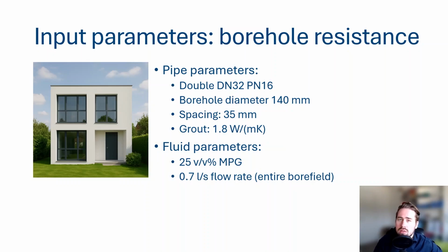For our fluids, we use 25% volume percent of monopropylene glycol, and we will use a flow rate for the entire bore field of 0.7 liters per second. Now, this last one will be important in this exercise. I'll come back to that later.